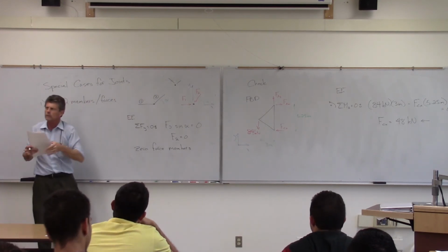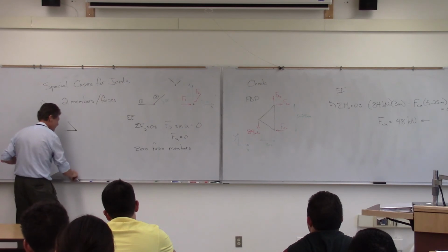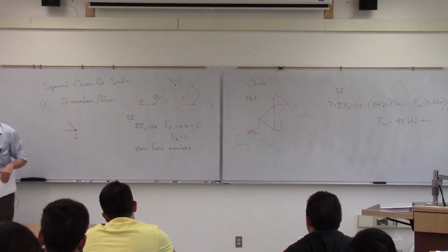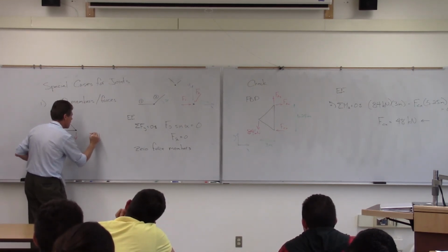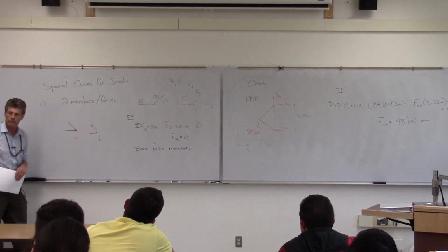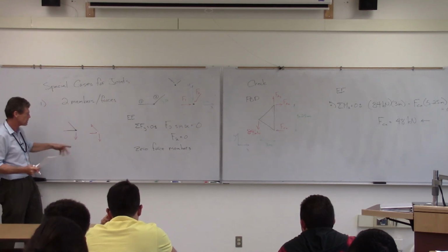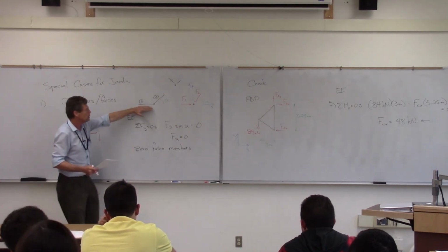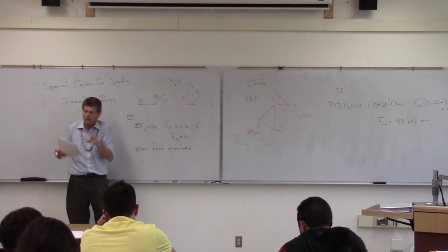Now, the reason why I bring up thinking about this in terms of forces is a lot of people will see something like this. Are those 0 force members there? No, there's 3 forces. When we consider the free body diagram, it looks like that. So you've got to be a little careful with it. It's not 2 members per se. If there's forces hanging on it and that sort of thing, when you get to that equilibrium problem, you realize I don't have 0 force members here. When I look at this situation, think about it in terms of forces.